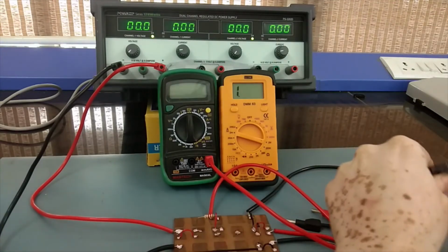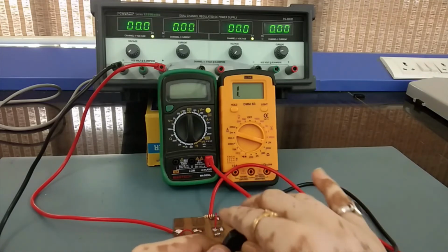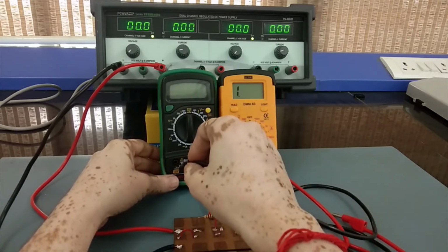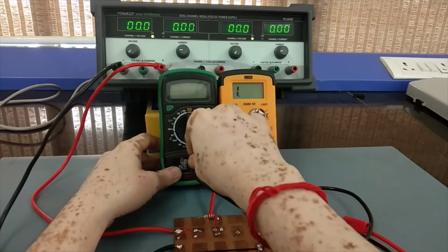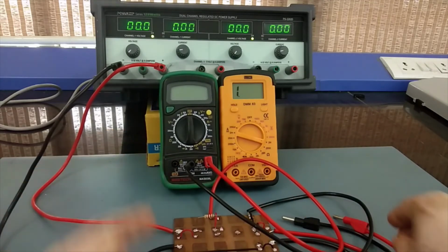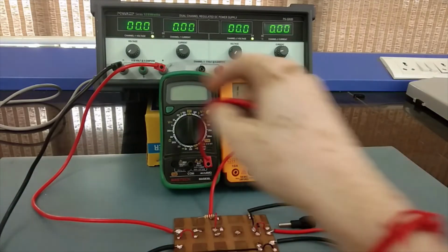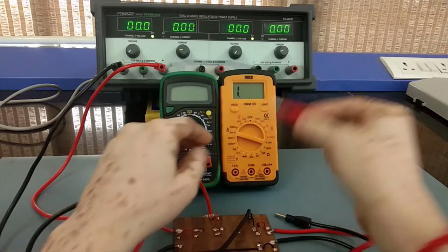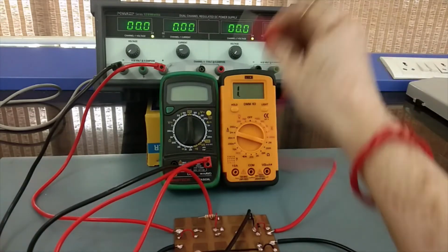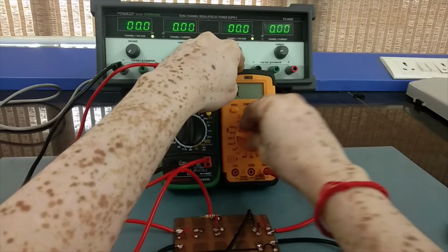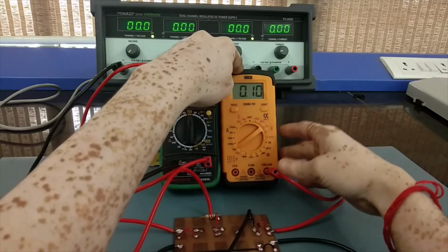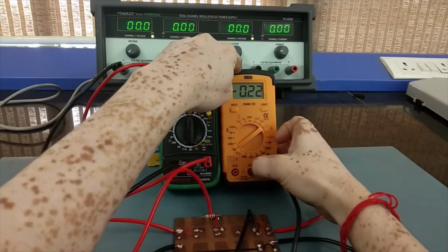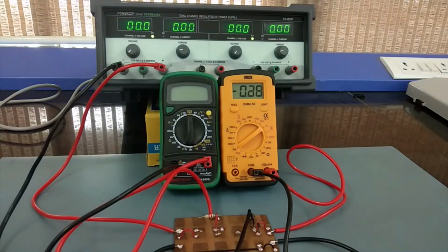So for a digital ammeter there is no problem, you will be finding a minus mark, but for a unipolar single polar analog multimeter, it may damage the multimeter. Okay, so connect it to the common terminal. All right, and now you want to measure the voltage across the diode. So for that you take this anode to the voltage terminal. I will put it in volts, 20 volt range, and the circuit common is connected to the common terminal. So that's all with the circuit.